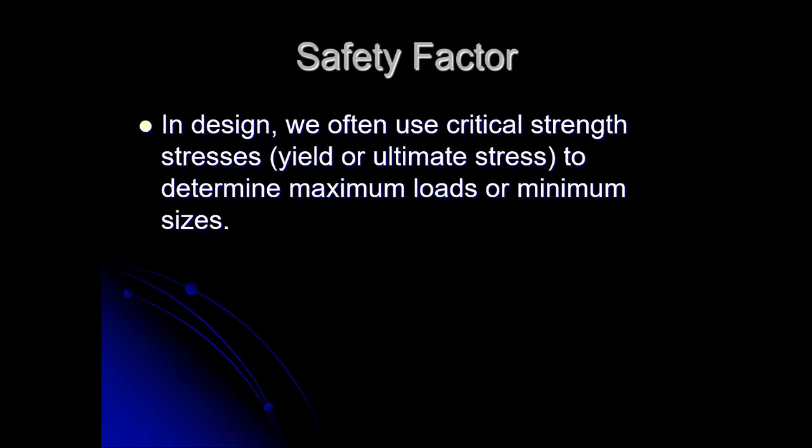Safety factor is a way of adjusting the material strength or adjusting the loads that we use. It works both ways to figure out what our minimum sizes should be for material, or what our maximum load should be.